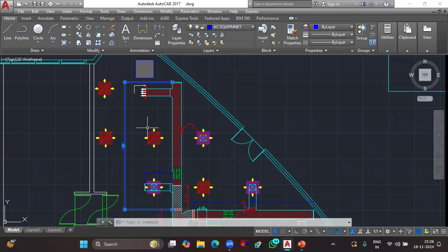So once again, guys, initially you need to start over with the flow path itself. For example, if you place a pump right near the well, you will get maximum flow rate and maximum pressure from the exact output of the pump. But if you connect the pump delivery port with a pipe and extend it to a certain distance, like 1 kilometer, once the water reaches the other end of the pipe, it will lose its flow rate and its pressure, isn't it?